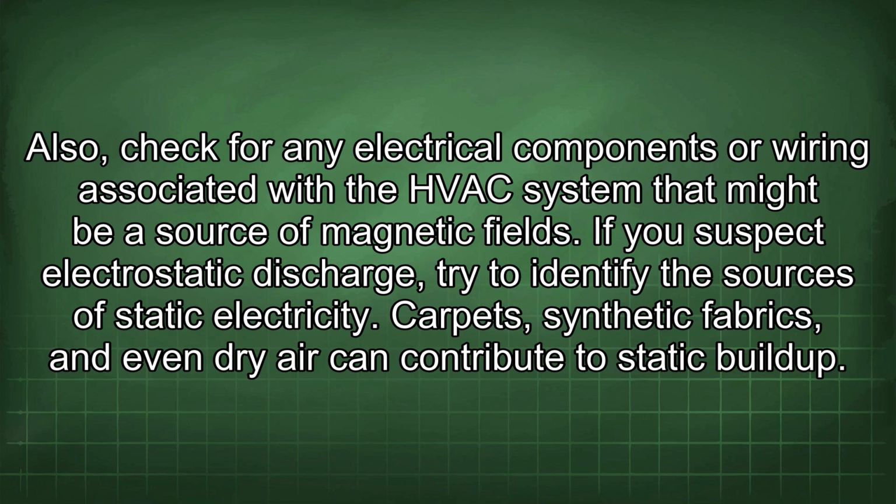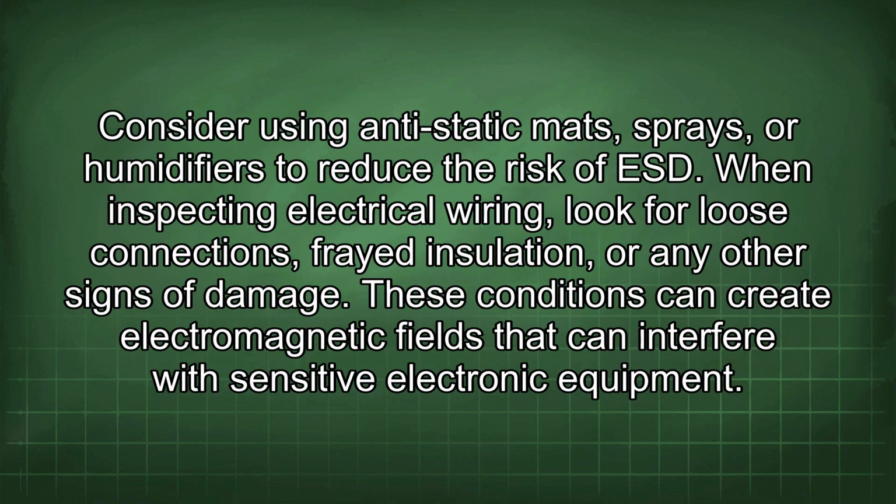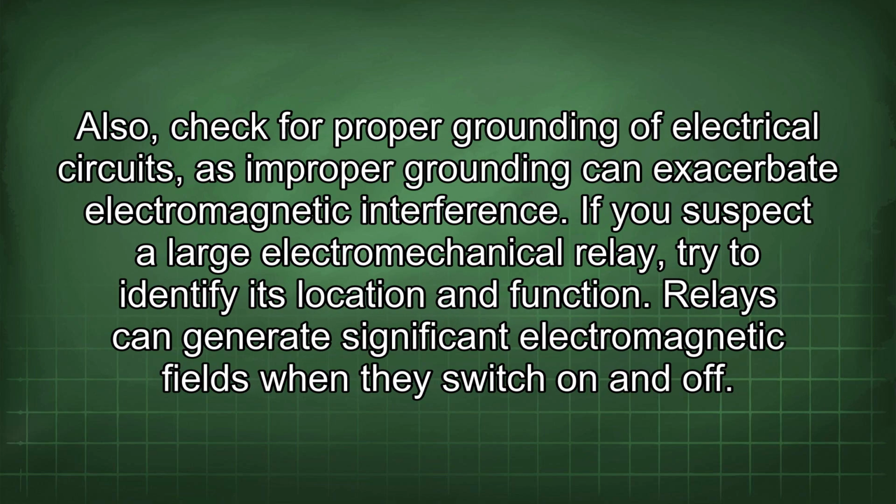Carpets, synthetic fabrics, and even dry air can contribute to static buildup. Consider using anti-static mats, sprays, or humidifiers to reduce the risk of ESD. When inspecting electrical wiring, look for loose connections, frayed insulation, or any other signs of damage. These conditions can create electromagnetic fields that can interfere with sensitive electronic equipment. Also, check for proper grounding of electrical circuits, as improper grounding can exacerbate electromagnetic interference.